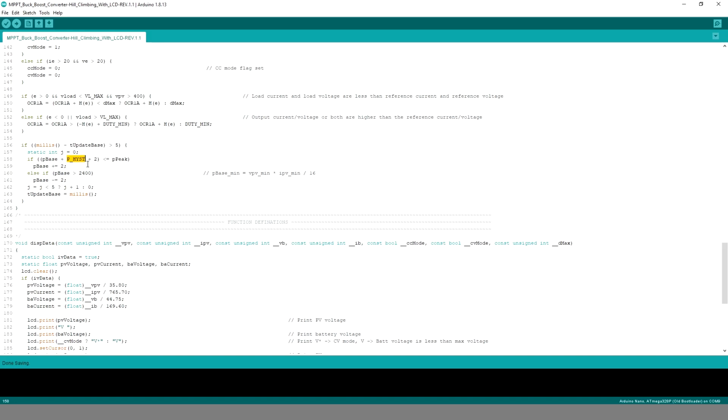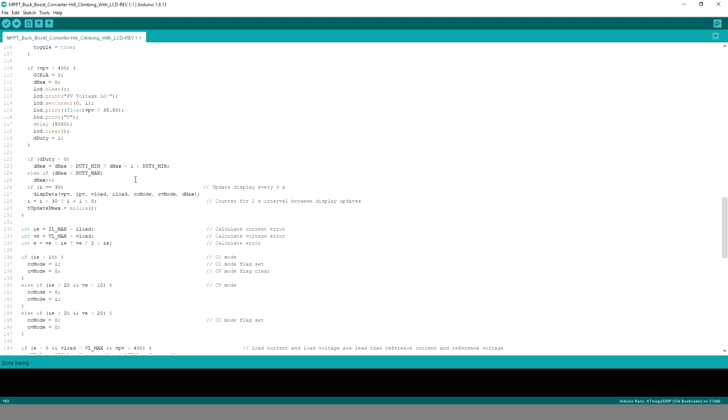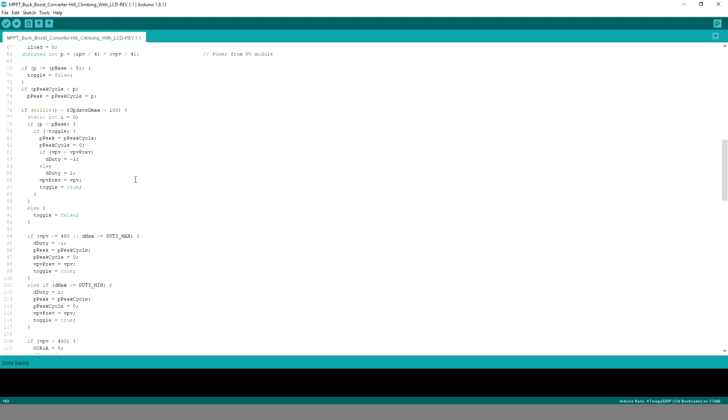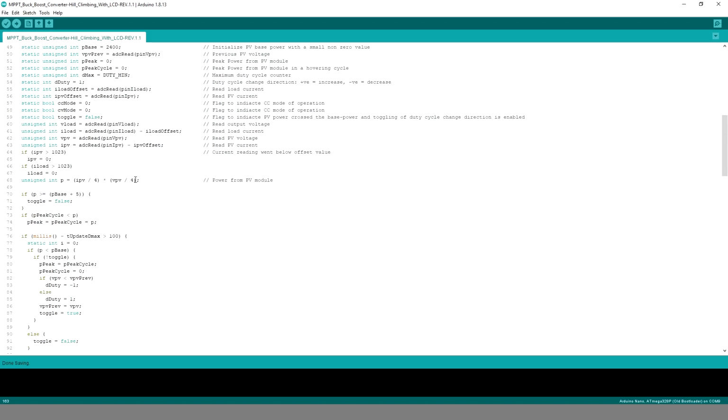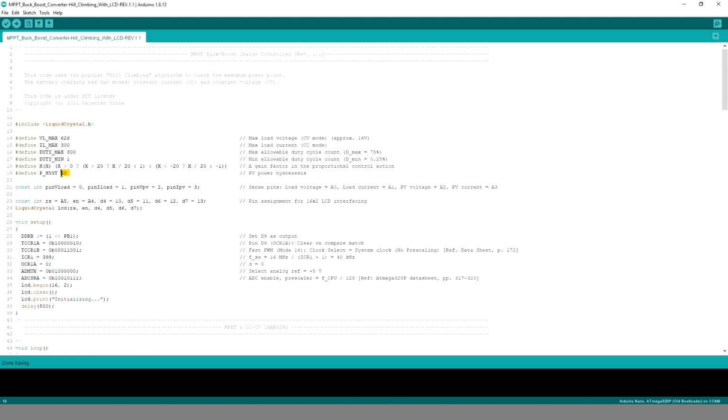The hysteresis value should be adjusted carefully. If it is made large, then the power will hover over a wide region and we will observe a big fluctuation in the output. On the other hand, if we set it too small, then the microcontroller won't be able to lock itself in the position over the base, and starts hovering between the open circuit point and the short circuit point. In my case, I got a stable output with 50.